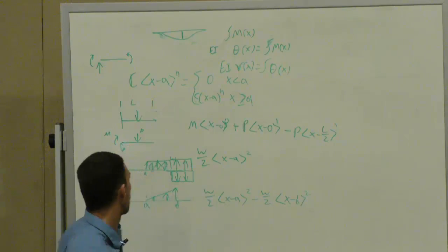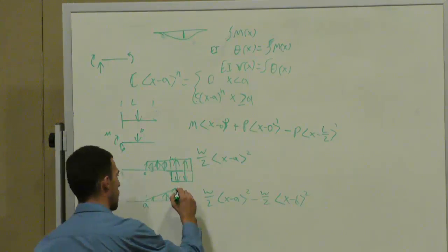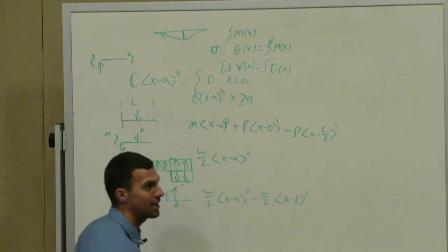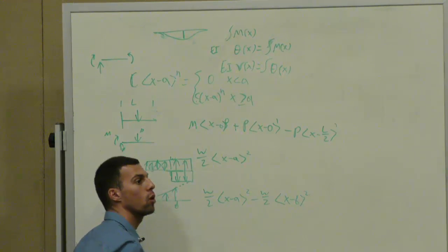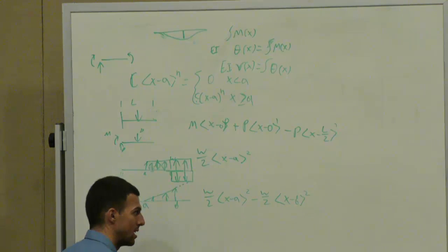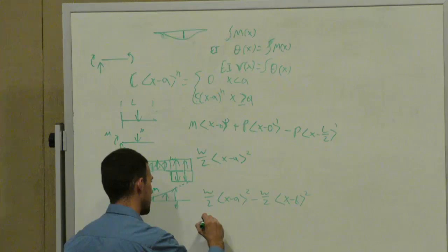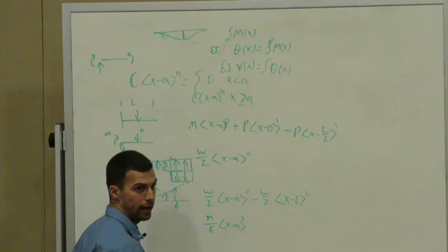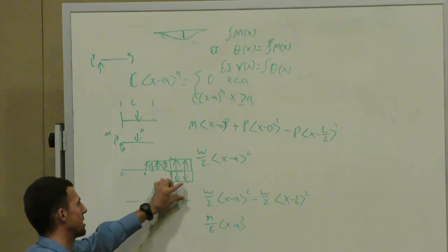Okay, so once again, the Macaulay function doesn't see the end of this. It assumes that you continue this way, at the same rate from that same point. So the Macaulay function for a single linearly distributed load that does stop at the end of the beam, if it has a slope of lowercase m, is lowercase m over 6 times (x minus a) to the third. So how do we get rid of this portion of the load that is not really there?